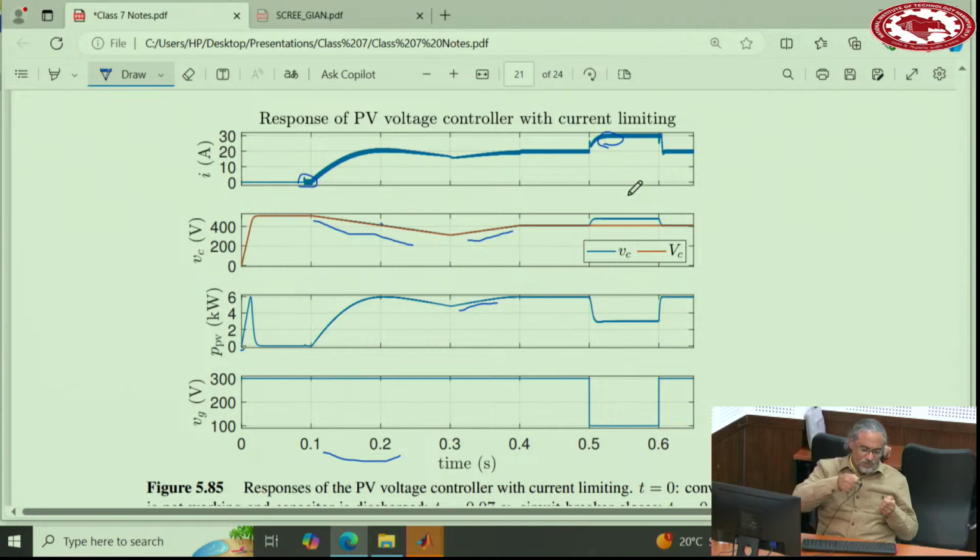And the capacitor voltage is across the PV. So as the voltage goes up, the power goes down. So it's a very nice behavior. Because the grid cannot absorb a lot of power since its voltage is very low during this time. So as a result, the capacitor absorbs power and its voltage goes up. So the voltage across the PV goes up and its power goes down.